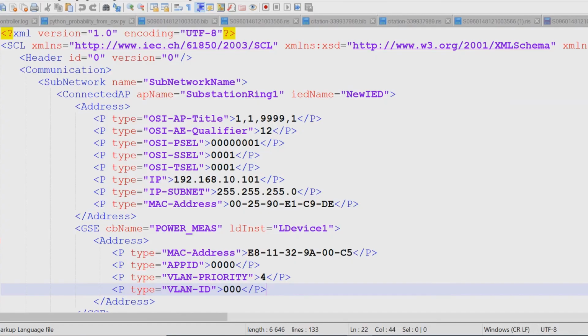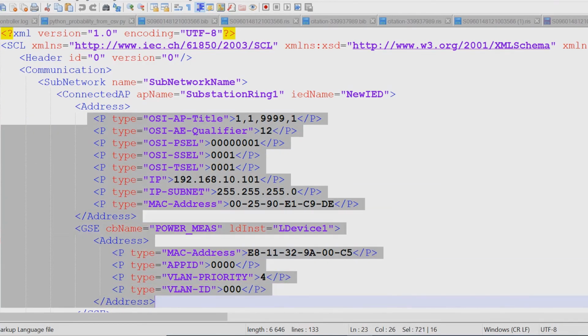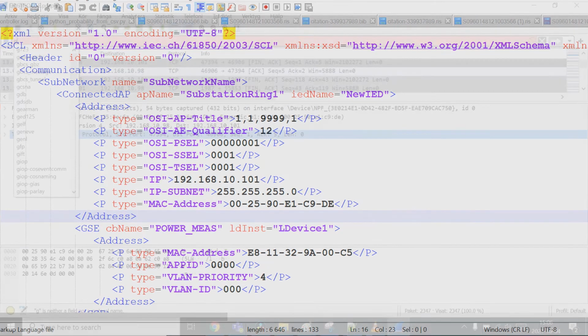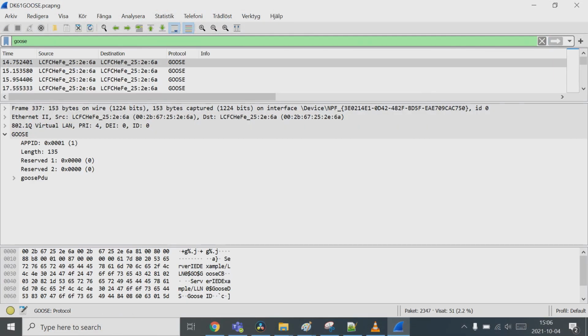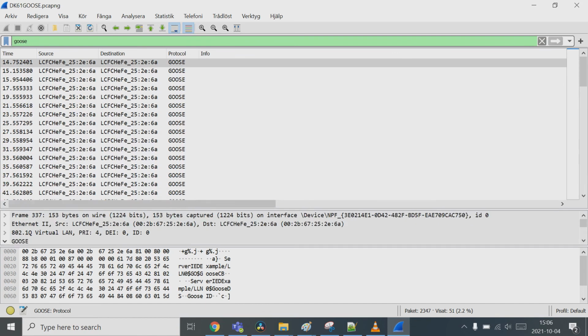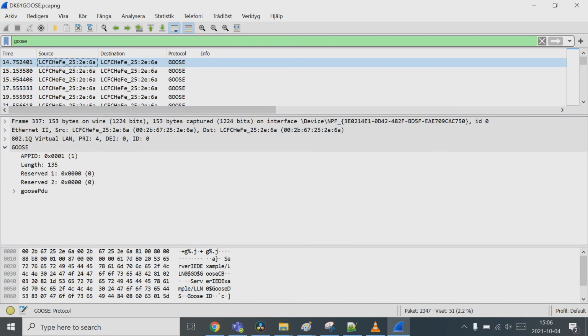Check and debug the configuration file with the CID extension, both for the server and client sides, find possible flaws and inconsistencies before actually using it in reality. Check the algorithm structure of the energy management application to find some bugs and shortcomings.